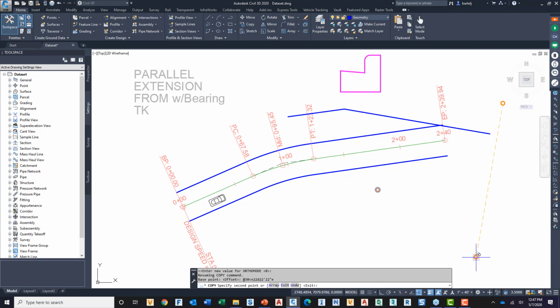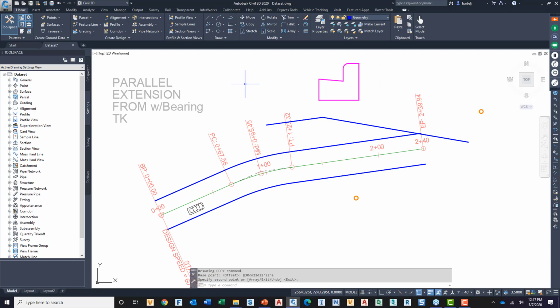So it goes up to there, and then I can go ahead and drop it. Okay, so we don't have to necessarily create construction lines to get the points we need. I could do the same thing. I could start drawing a line, copying a block, rotating something around a point that is from another location. There's another option we can use that's kind of from, but multiple steps. It's something we would use maybe more for details, but that's TK for tracking.